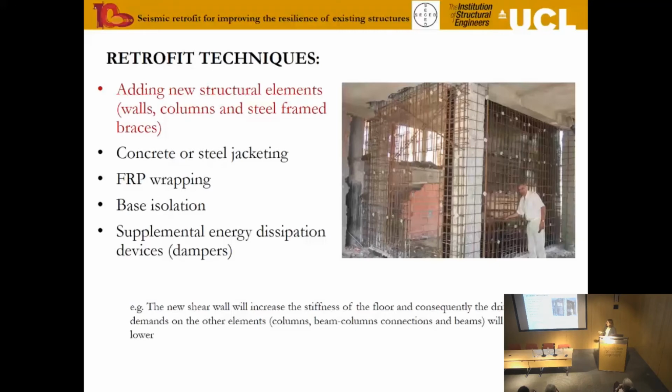I'm just going to mention base isolation and supplemental energy dissipation devices. These are used for reinforced concrete structures. Base isolation in particular has become quite popular in some of the retrofitted or new buildings in Italy post the Aquila earthquake. However, they're typically very expensive, and the expense is such that it's prohibitive for most residential type constructions, so it would be used mainly for critical infrastructure or critical buildings.